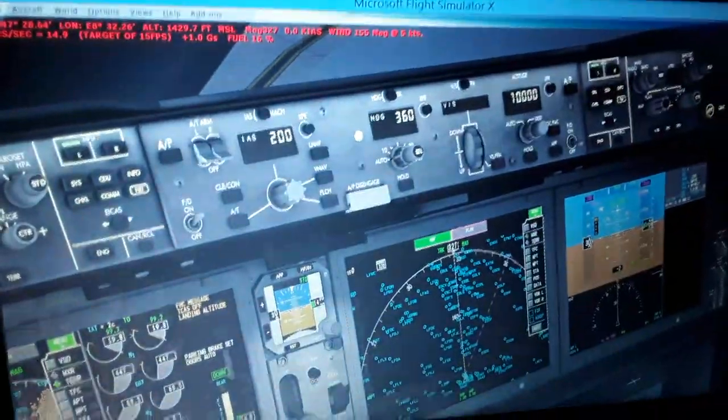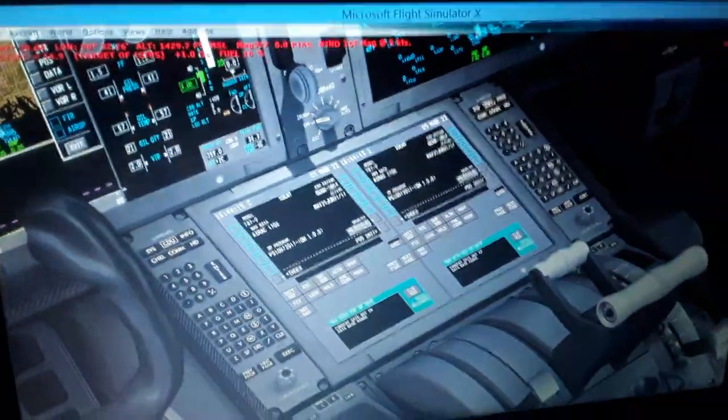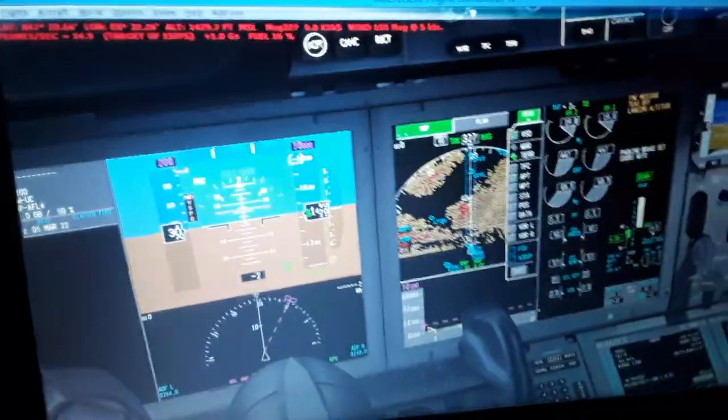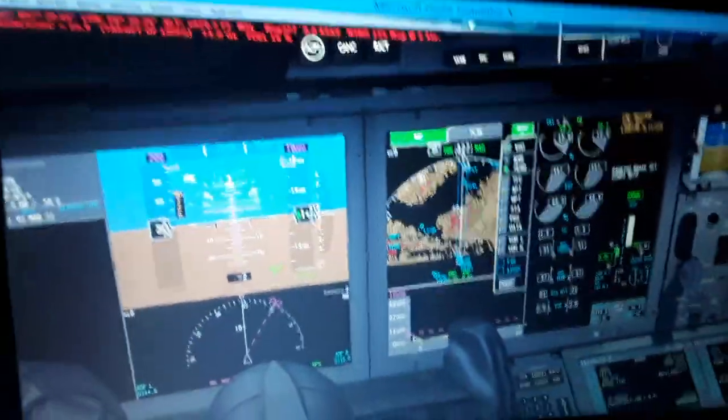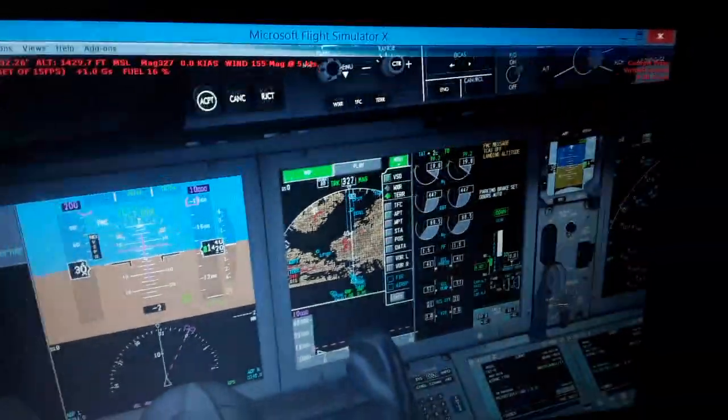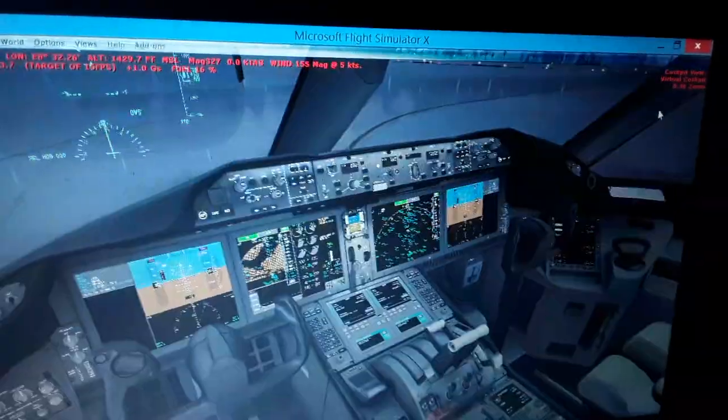Over here we have some modes from the flight management computer so we can follow the flight plan. You will see later the magenta or purple lines over here in the navigation display, also in the HSI, of the flight plan we're gonna create. So it's gonna be waypoint by waypoint navigation. The waypoints are horizontal and vertical navigation features.